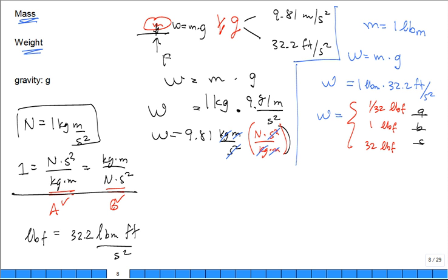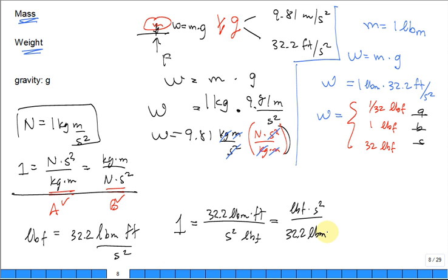How do you know that? How do you know what a Newton is defined as? Somebody defined it. There you go. All right, so what you do is you see that I can use 1 unit conversion factor as either 32.2 pound mass foot per second squared per pound force, lbf, or it's equal to pound force second squared per 32.2 pound mass foot. Can I use either version A or version B? Are they the same? Professor, they're not the same. Look, one's got a 32 in the numerator and one's got a 32 in the denominator. How can they be the same?